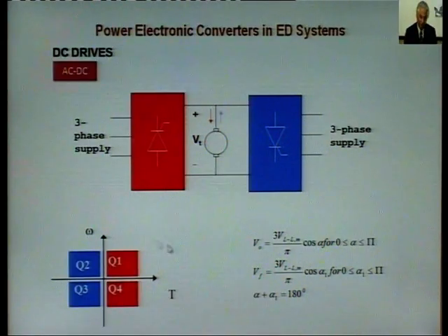That is why it is a double bridge configuration. One is a thyristor rectifier, another is a thyristor inverter. The inverter is supposed to have its configuration differently than the rectifier bridge, and this can always supply 3-phase supply to the power system. So, this is the beauty of the system.